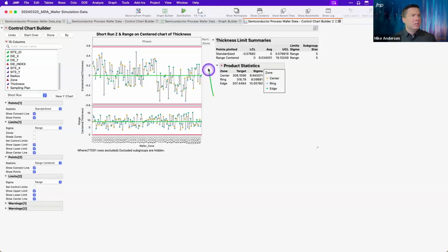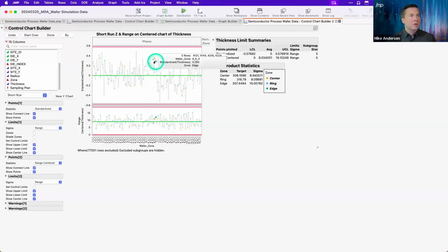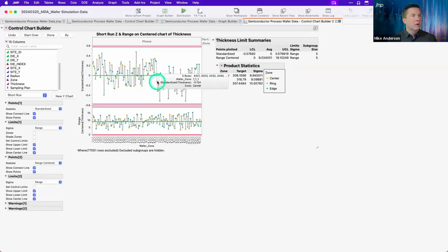The advantage here, you can see really clearly, this shift pops out, and we can look at it and go, okay, these 3 groups appear to be from the same wafer. Those are from lot 6, wafer 5. And if we look down here, oh dear, lot 7, wafer 1 had a big old jump, and it stayed there through 2 lots and then bounced back up. So we can start seeing the trends and patterns that indicate health or changes in our process much easier with this. More importantly, those trends and patterns can also show us changes in the wafer topology.